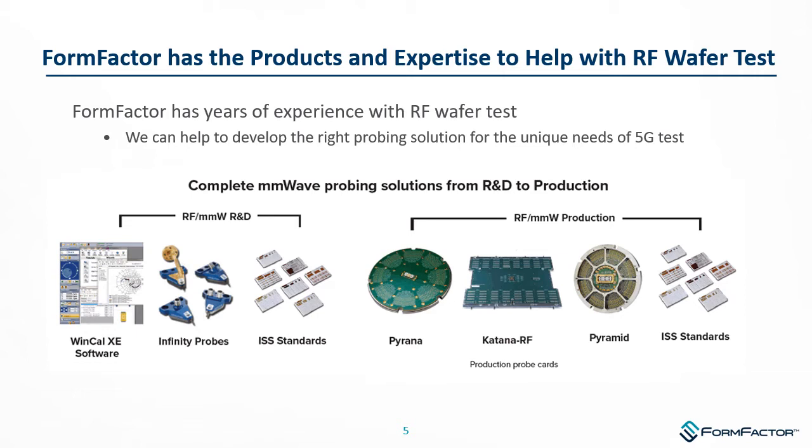We also have WinCal for RF calibration and RF measurement, as well as ISS standards that couple well with the Infinity probes. Once we move over to production tests, FormFactor has several different probe card technologies that are very useful for RF. This includes the Piranha technology, Katana RF, as well as the Pyramid probe technology, and FormFactor can help you choose the appropriate technology for your use case. In addition, we also have a standard suite of calibration standards that we can manufacture that will match your DUT layout.